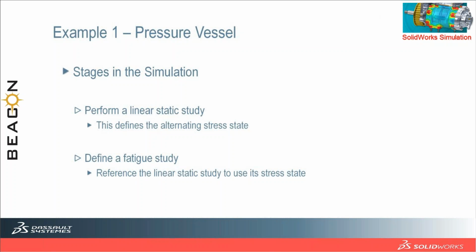See, usually we predict failure by comparing with respect to yield strength. If the stress is below the yield strength, we say that it's a safe one. It may happen that because of only a single type of loading it may not fail. So we want to check what will happen if I go for fatigue analysis, where I have some number of cycles.